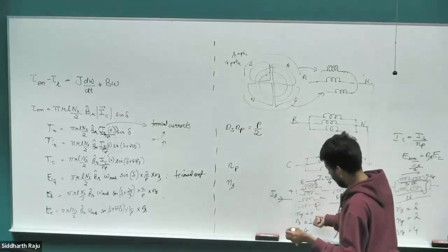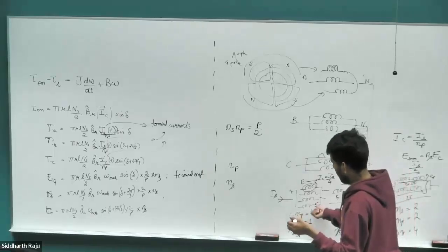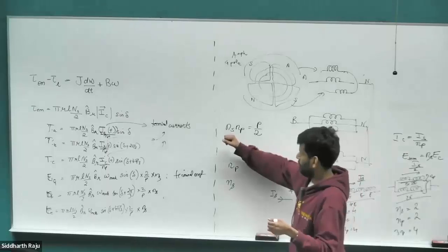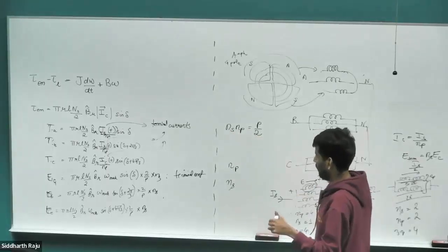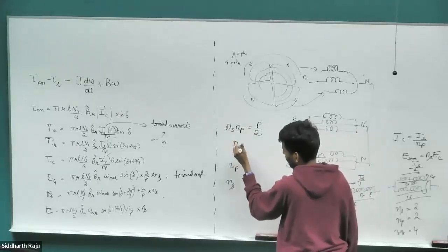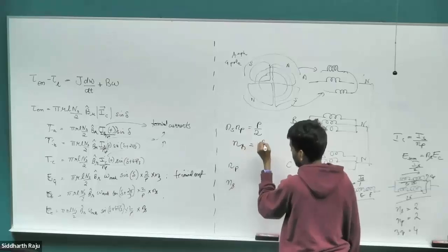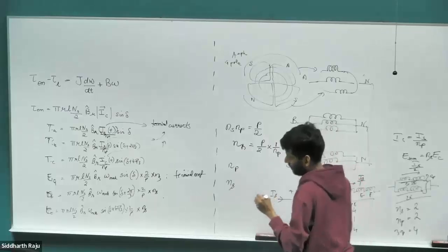And all the combinations can, of course, be reversed by getting Np times Ns. Right? Number of possible series-parallel pathways, number of possible series pathways. You multiply them up, you would end up with your same pole pairs again, because that's the number of coils you started out with from the beginning. So from this expression, with your Np, let me substitute for Ns. Ns is P by 2 times 1 by Np.